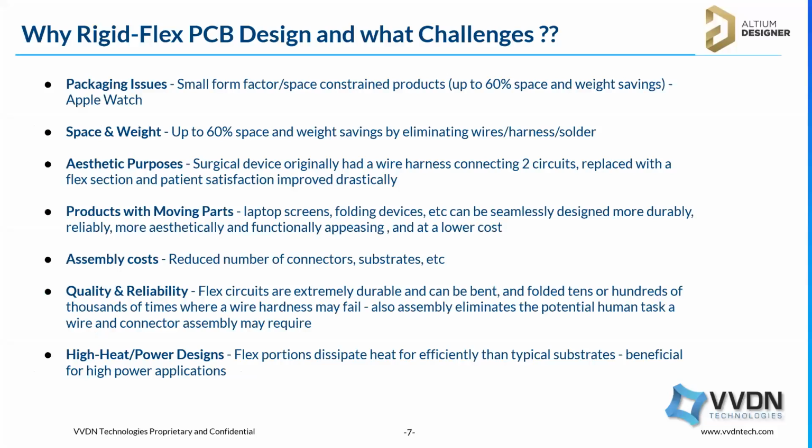So why Rigid-Flex PCB designs? Packaging issue. If you are facing any packaging issue for a small form factor, or a space constraint is there, at that time we can reduce this. Up to 60% space or weight we can save through these Rigid-Flex designs. For example, we can build a smartwatch.